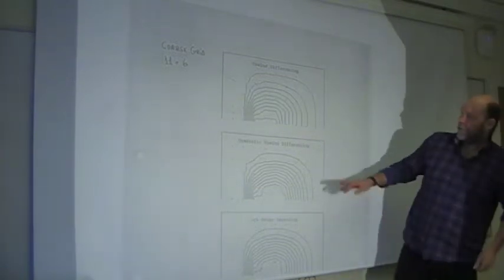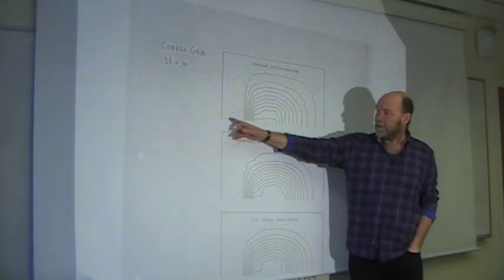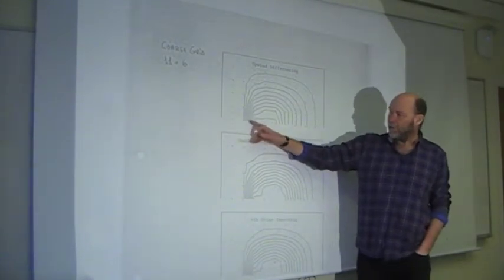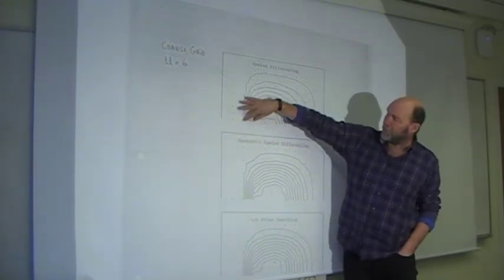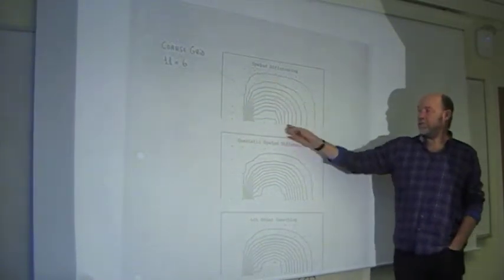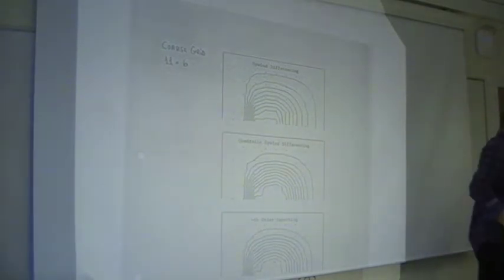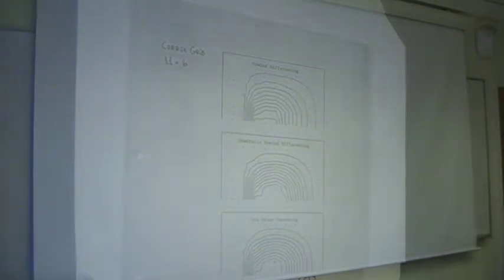So this is the iso line, so this concentration, constant, and then a jump, and then constant. And you see how this sharp gradient gets smeared out over the entire gap on the other side. So first order upwind, very diffusive.